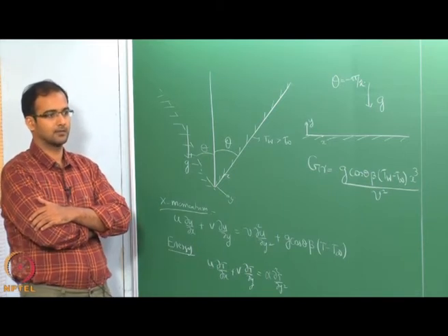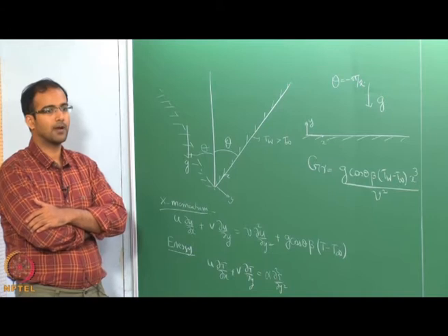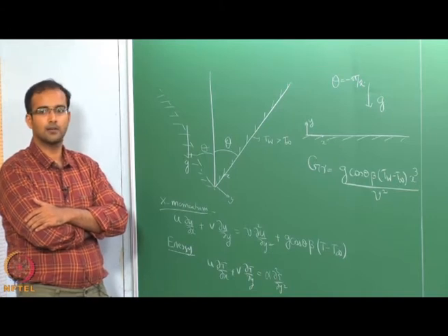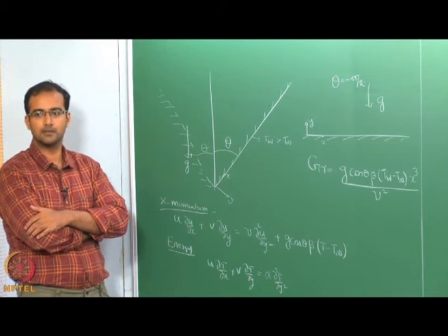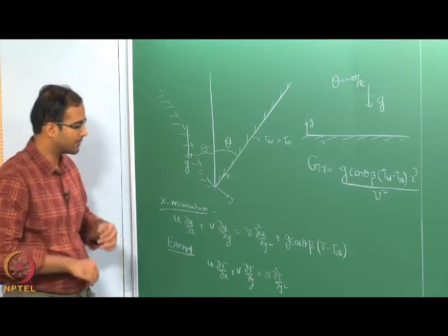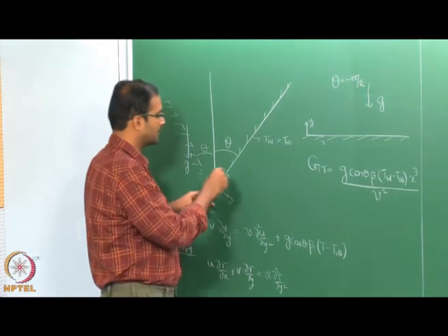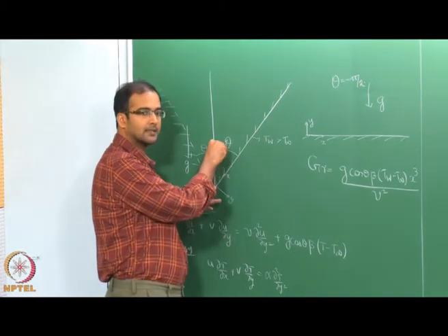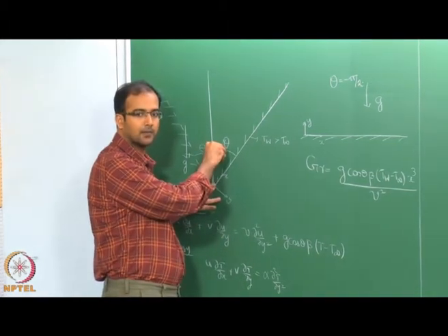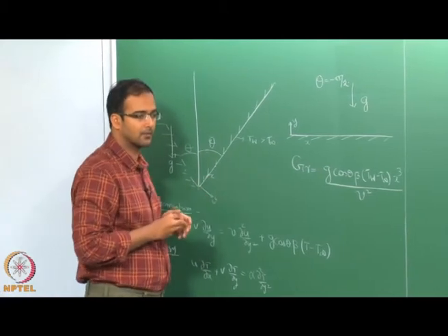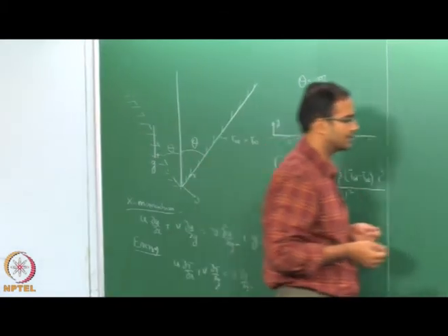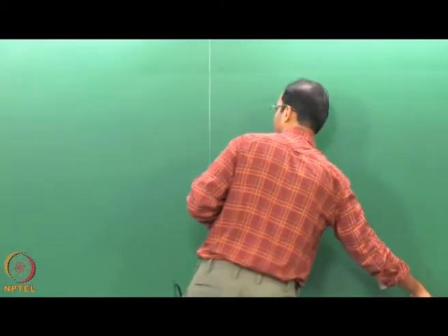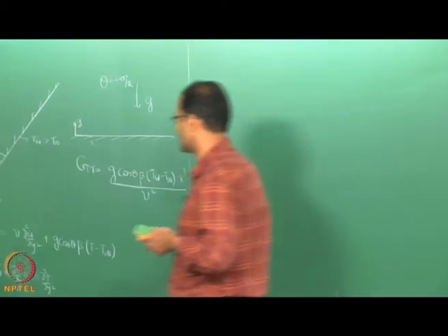We cannot, because as you see the buoyancy is now acting in the y direction. There is no buoyancy at all in the x direction. So, therefore, we have to be careful, okay, for reasonably small inclinations the earlier approach is okay, but if you have a completely horizontal plate, then we have to redefine the governing equations.